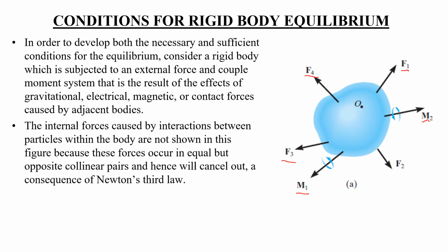As we have studied, we can assume that this body is a point which has the same mass and no dimensions. When you assume that this whole body is just one point mass, then all of the forces are acting on this mass. If the body is in equilibrium, then all of the forces combined must cancel each other out, and so the resultant force must be 0.